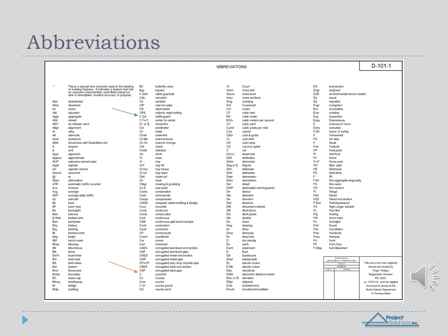Abbreviations are used in an effort to keep plans neat and organized. Abbreviations reduce the amount of clutter on any plan sheet and allow for a clearer, more precise drawing to be made. For example, instead of having to write in cattle guard on a plan sheet, it can be referenced with an abbreviation, shown here next to the green arrow as CGD, indicating cattle guard. Using 3 letters instead of having 2 words spelled out, perhaps multiple times, helps to keep plans clean.